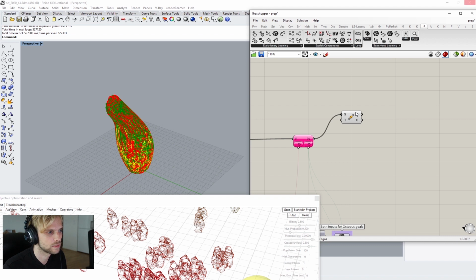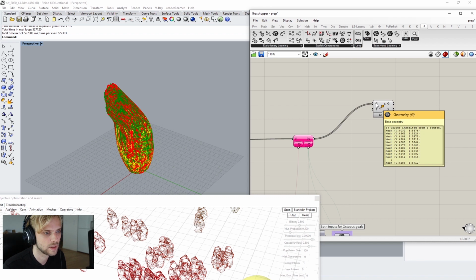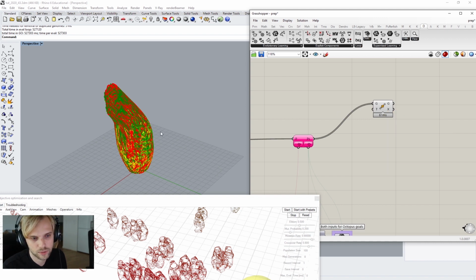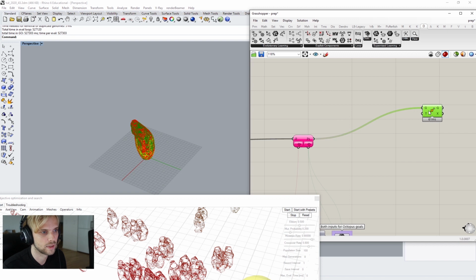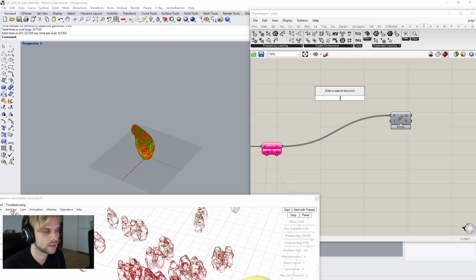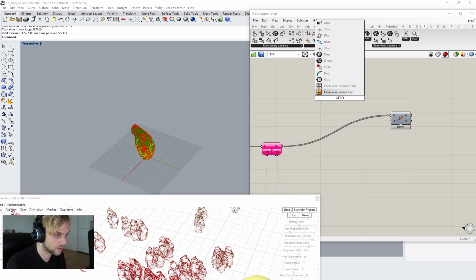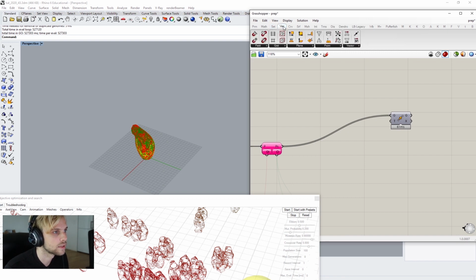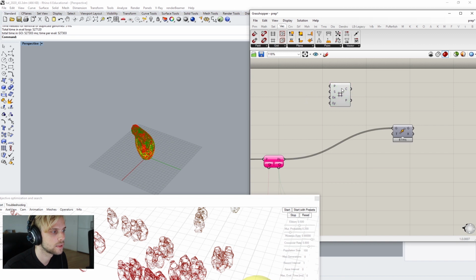Why is this crashing? Oh no. Okay, it's not crashing. It seems to be crashing. So I can move these 53 meshes onto some sort of a grid, right? So I will just create a grid. That's not how you create a grid. You go to vector, grid, square, onto a square grid, and I will say that the size of the grid is every 50 meters.